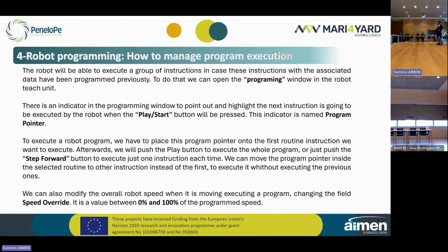From this window, we will be able to select a robot program saved on its memory, previously saved by someone, with the robot movements saved on it. From this programming window, we could select a robot subroutine, start to execute it to check if that routine is correct or not, and modify it or not, or just put the robot to work in an automated mode.